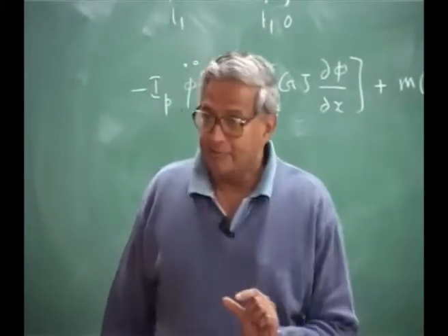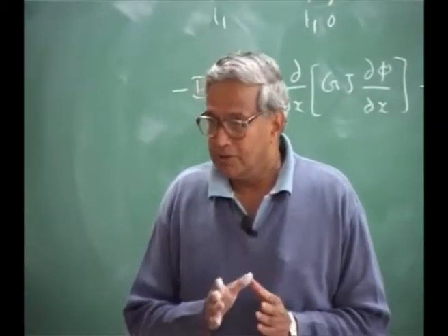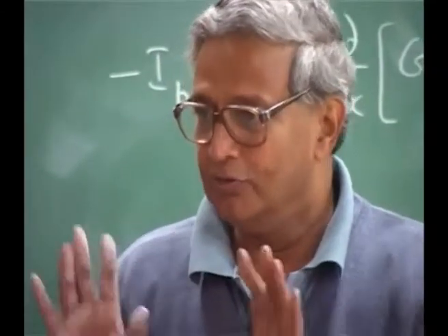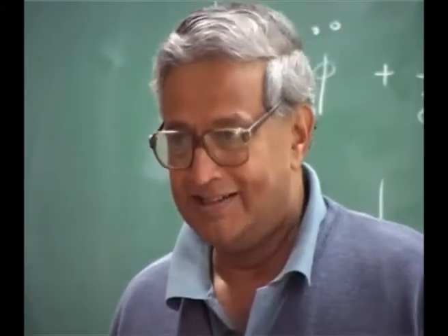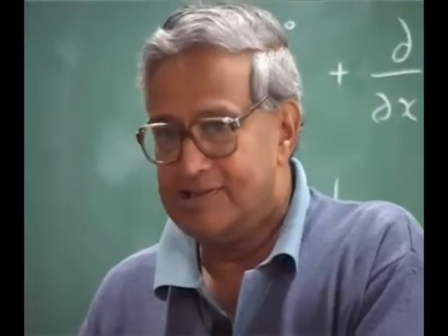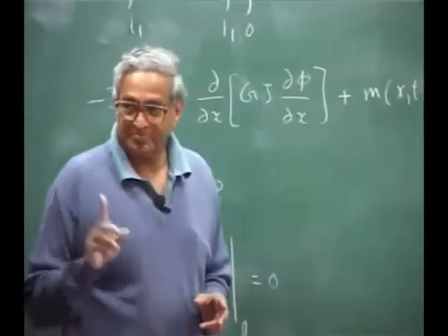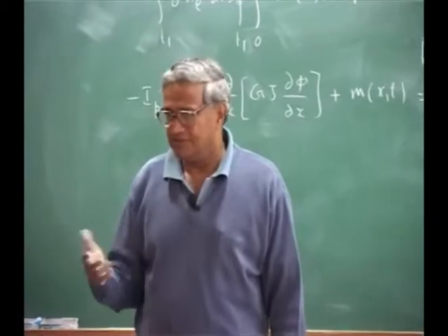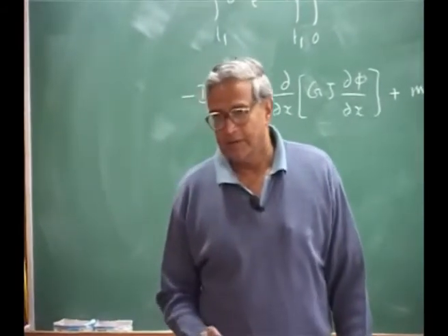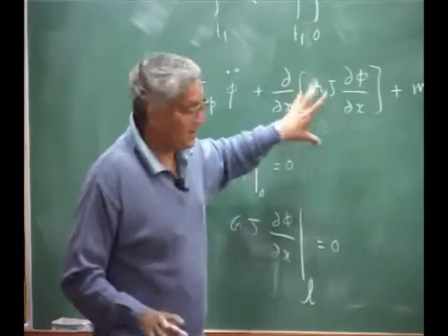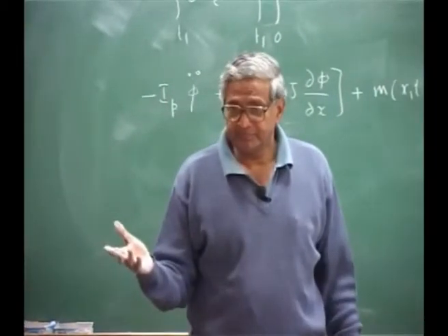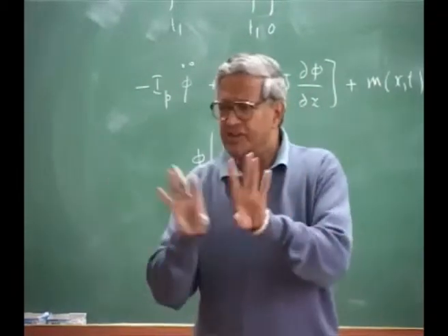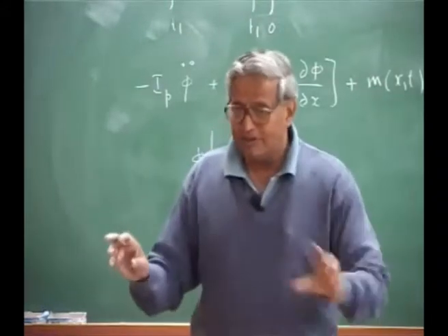Okay. Then comes the Sturm-Liouville theorem I told you about, what it says: if the equation is of this form, you will have solutions of this type. You understand? That is where that equation is applicable, but it is derived only for second order systems. But you will find that application in any book on differential equations and boundary value problems; they will deal with that. They give a solution for second order, but you can also apply it to fourth order. There are several conditions, such as orthogonality of the functions, etc. Those are generally proven for the most general problem. They will not be specific to the bending problem or the torsion problem.